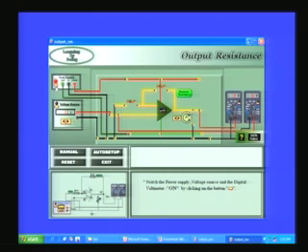Now, let me switch on the power supply, dual power supply, the voltage source, the multimeters, and now I will apply about 1 volt. I have applied 1 volt from the voltage source at the input, and you see the output is around 1 volt. Right. Now, what I am going to do is I am going to vary this variable potentiometer slowly, and you see what happens to the output voltage, which is measured here. You find the output voltage is now 0.5. So, previously the measured voltage was 1 volt, and now it is 0.5 volt. That means, it has become V0 by 2.